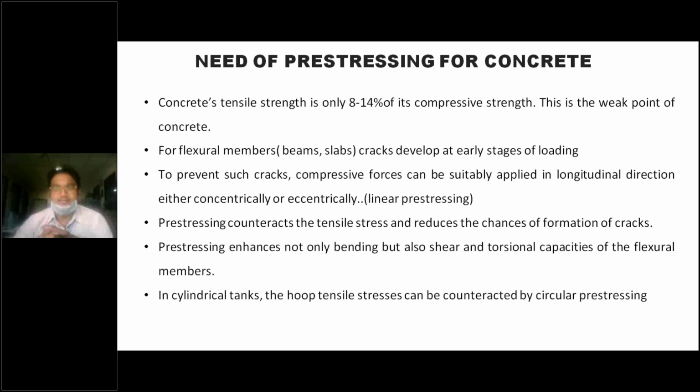And in cylindrical tanks, let's take an example. The hoop tensile stresses can be counteracted by circular pre-stressing. So not only in longitudinal members, even in circular tanks, pre-stressing technology can be used, where the pre-stressing is applied to counteract the hoop tensile stresses.